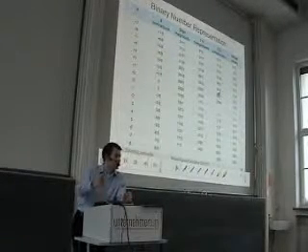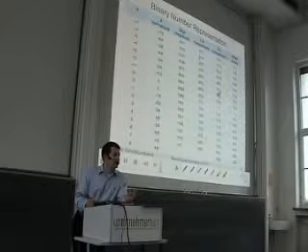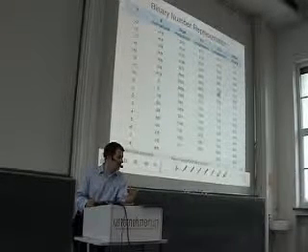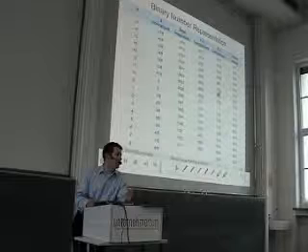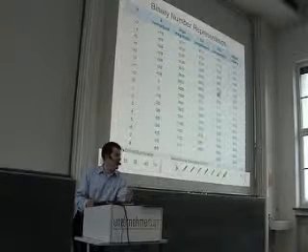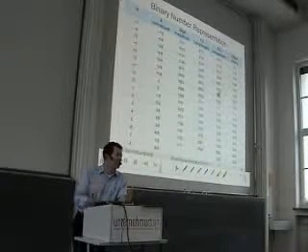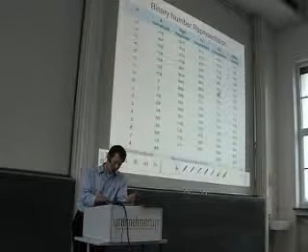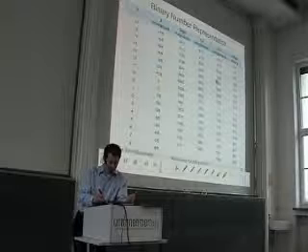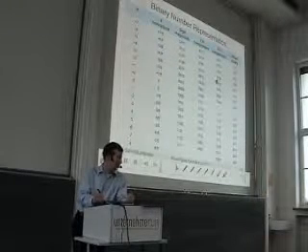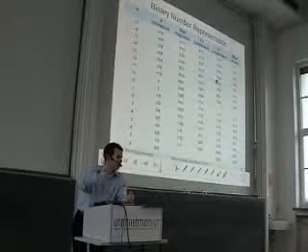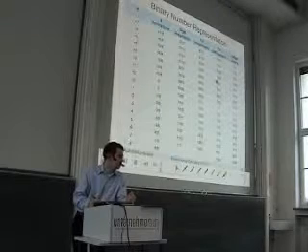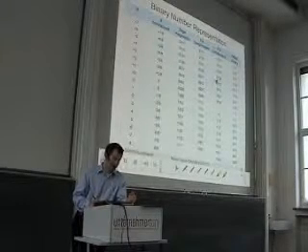If we go to negative numbers, then we have to take the respective positive one, we have to invert all bits, and we have to add a single 1. So, for instance, coming from one positive number to the respective negative number, invert all bits plus 1. This is the 2's complement representation.